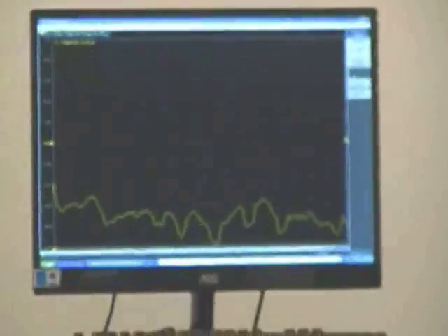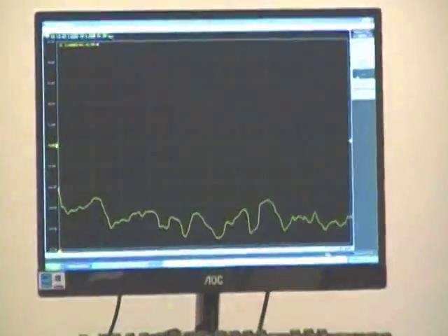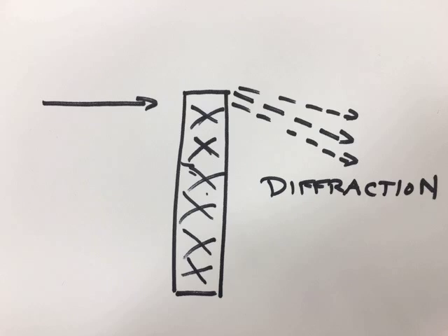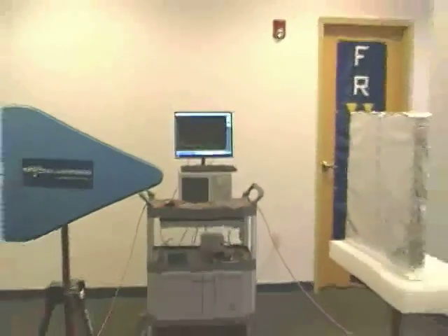We're going to zoom in and you can see the intensity has gone down dramatically from the zero line. In fact, it's gone down between 15 and 20 dB compared to the direct path. It's feeble intensity and sets a stringent limit to the amount of edge diffraction. There's very, very little front scatter happening when you place a metal wall in the direct path.